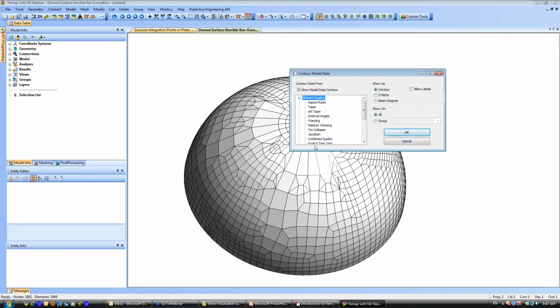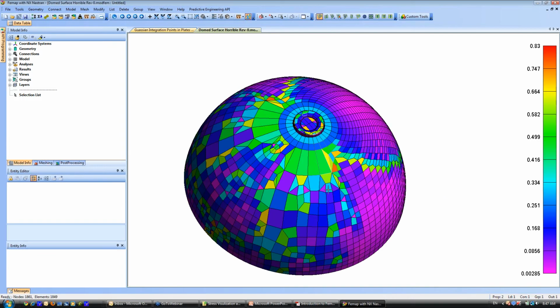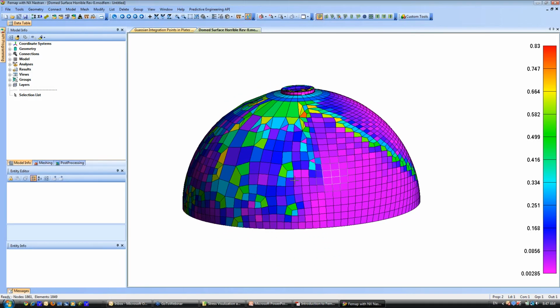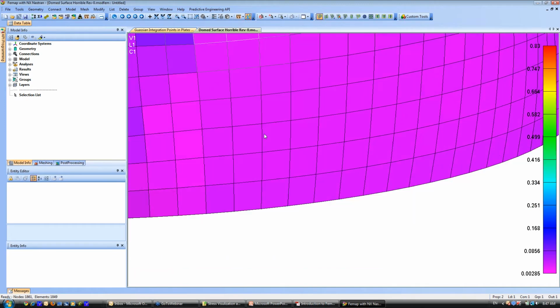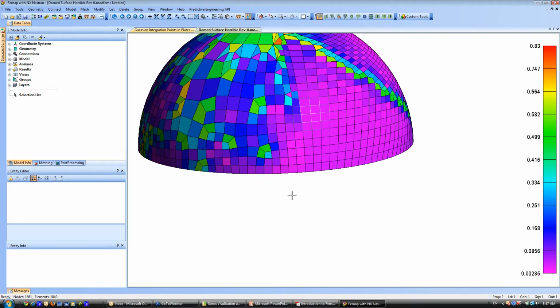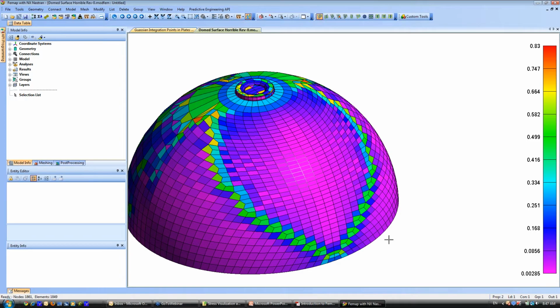But what I'm going to use it for here in this seminar is you can do element quality. Heck, you can even do explicit time step if you're doing explicit work in LS-DYNA. But there's our Jacobian, and we can contour the Jacobian over the model. And we have a range of near 0. And you go, what would be a 0 Jacobian? Well, check out that element. That's a perfect 1 by 1 Jacobian. And then everything sort of degrades. And it's picking up this little fan here. But it's not bad. It's around 0.5.